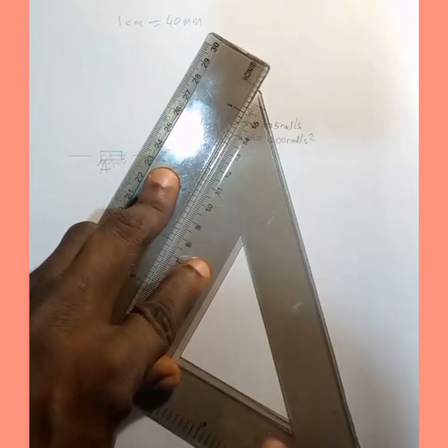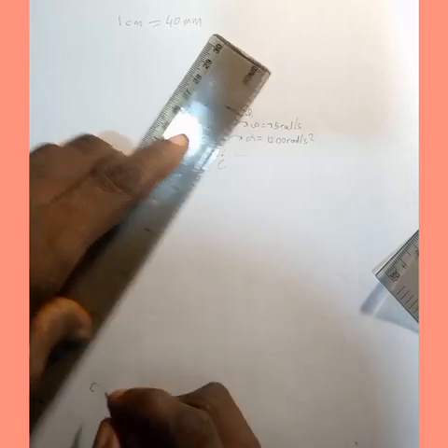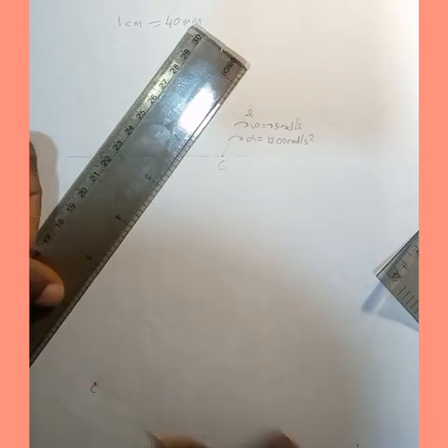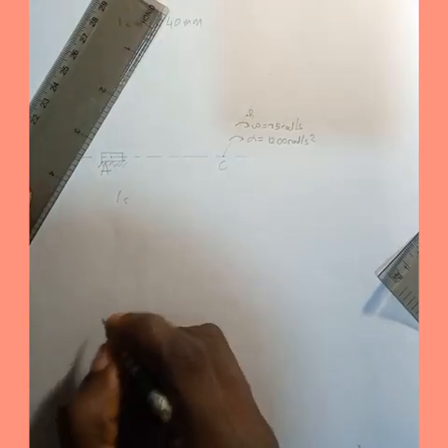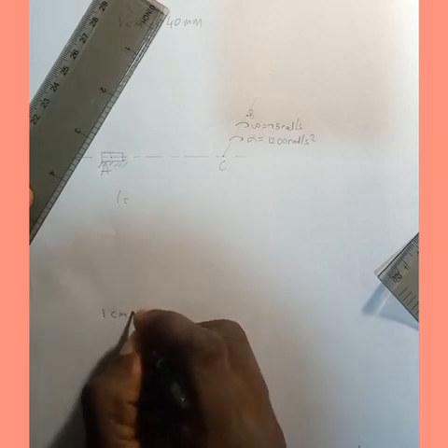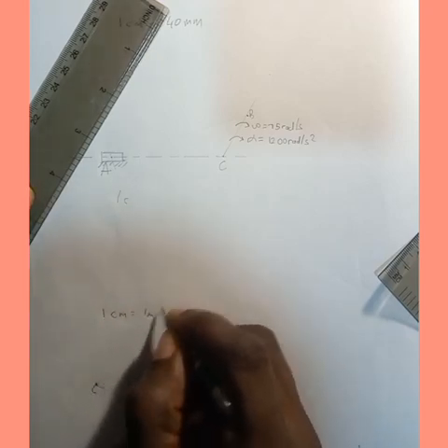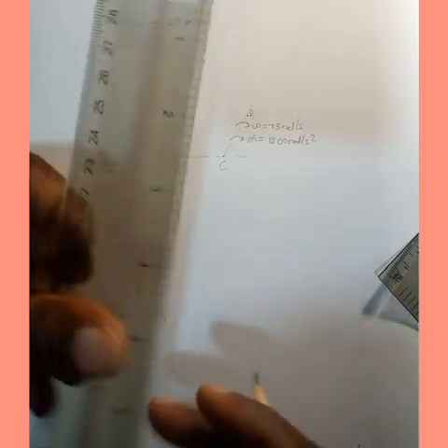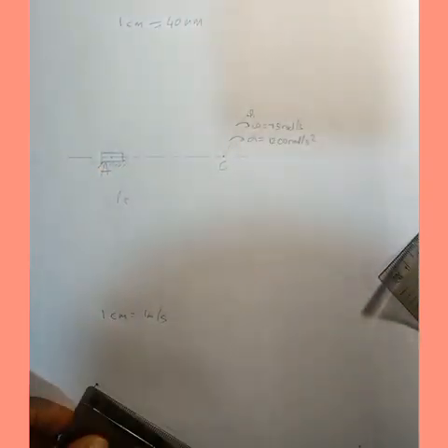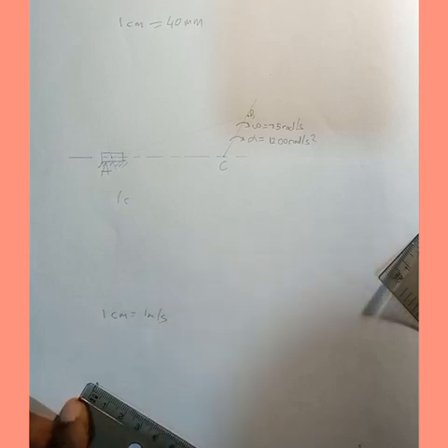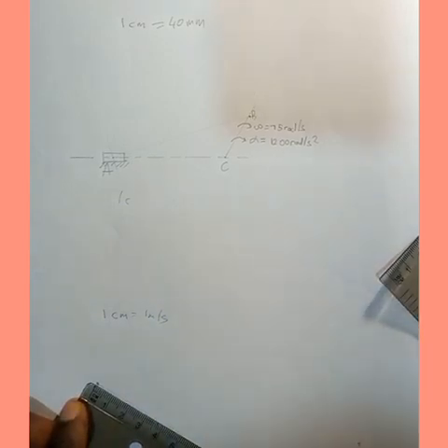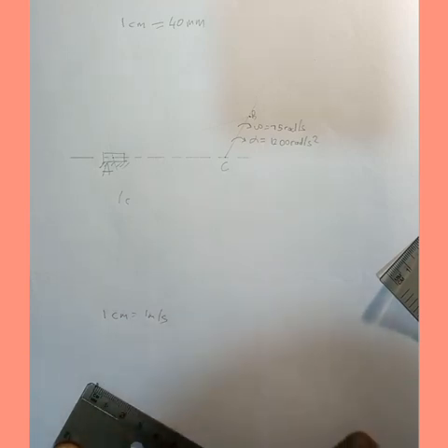Now draw this line which is perpendicular, so the starting point is point C, and this line is perpendicular at point C. Don't forget we have chosen the scale of 1 centimeter equals 1 meter per second. And since we have the velocity at 7.5 meter per second, it means we are going to measure 7.5 centimeter, from here to here. So now this is for your crankshaft BC.